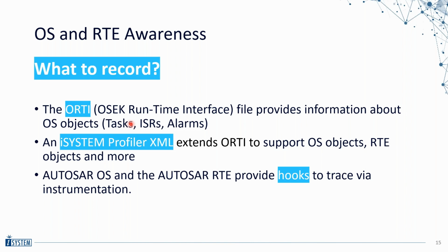And the first step is the so-called ORTI file. ORTI stands for OSEK Runtime Interface, and OSEK is the standard that came before AUTOSAR. So all your AUTOSAR operating systems still create an ORTI file. If you generate the OS, then an ORTI file can also be generated.